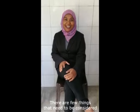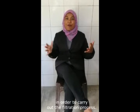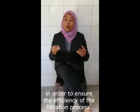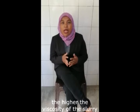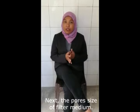That's it. There are a few things that need to be considered in order to carry out the filtration process. Firstly is the slurry. Slurry plays an important role in ensuring the efficiency of the filtration process. The higher the viscosity of the slurry, the lower the rate of filtration will be. Next, the pore size of the filter medium.